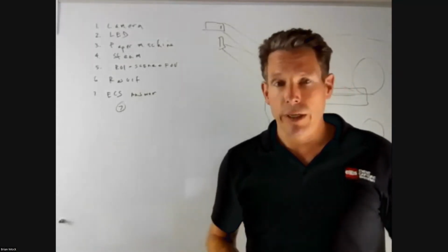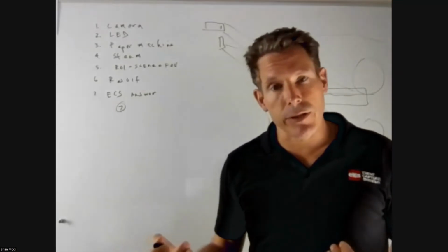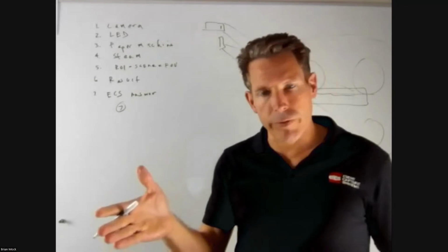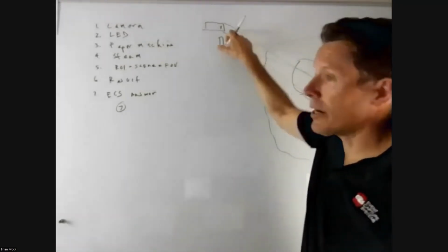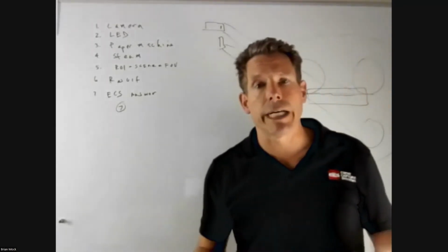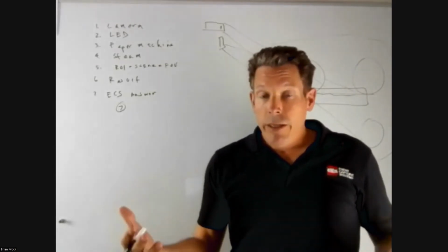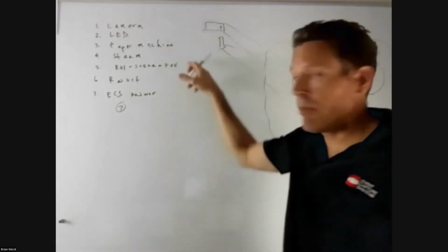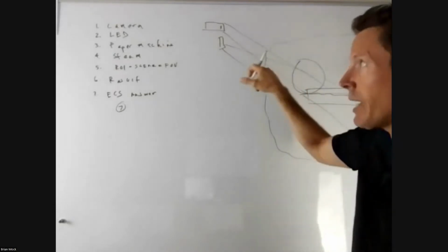What does that do? Well, NIR, at the wavelength that we use, which is still sensitive to the camera sensor, is a longer wavelength of light. So it's able to penetrate through the water vapor in order to hit my region of interest or my scene, and then bounce back so it can be received by the sensor. But no normal NIR light is going to work, because even though it has the advantage of the longer wavelength, the challenge is I need to produce enough NIR in a certain way that it's able to make it through the steam, not stop at the steam, get here, and then bounce back again.